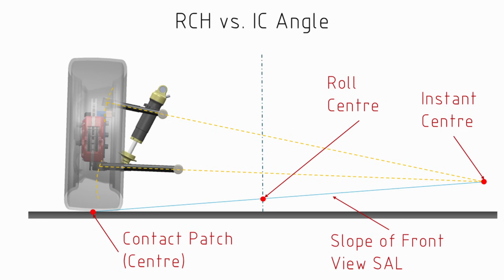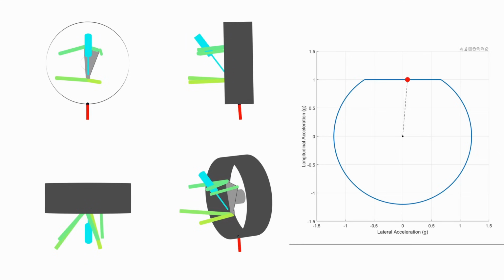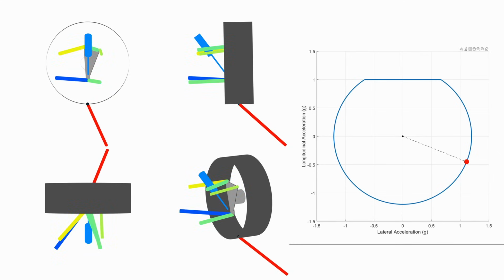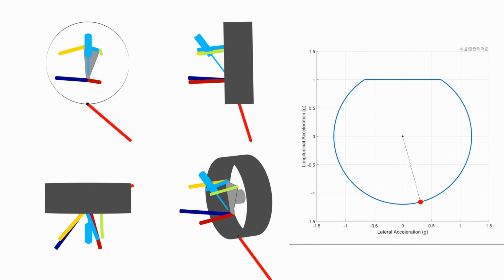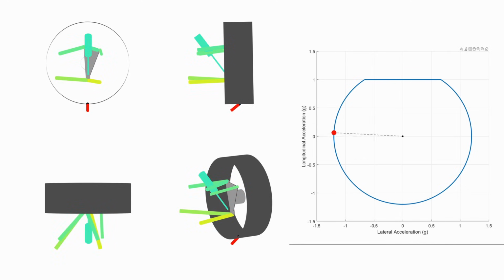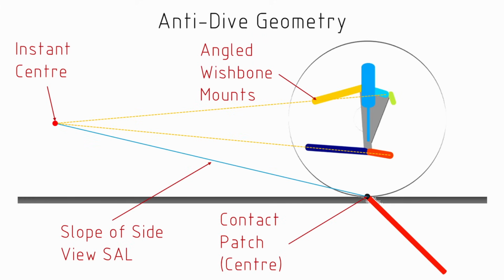And what we're saying is that the slope of the A-arms affects the load that's going to be going into the spring. To show this, I've created another version of the suspension system that has a significant amount of anti-dive in the front suspension system. To determine how much anti-dive we would have, we would take a line that joins up the chassis mounts of the wishbones, upper and lower. We would have one line for each, an upper and lower line.